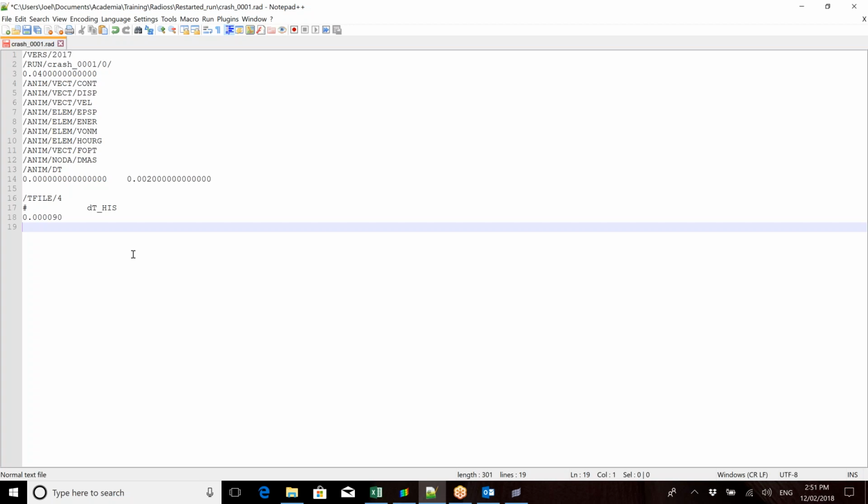And then when you reopen it, you can go into the control card section to see what's been selected, and you can also select some more if you'd like to get an understanding of the output. But if there's an output here that you don't want and you take it out, then it could mean that you missed some information. So I recommend just keeping all the defaults and only adding in more should you wish. And you can physically type them in yourselves as well if you want to do that.